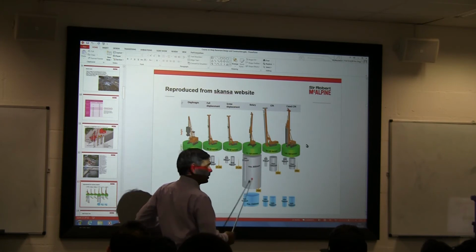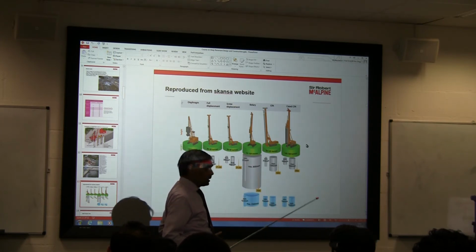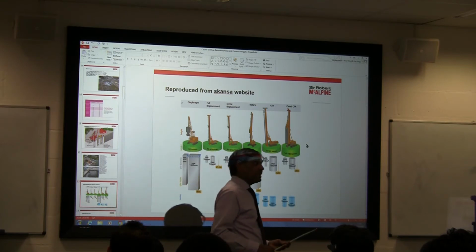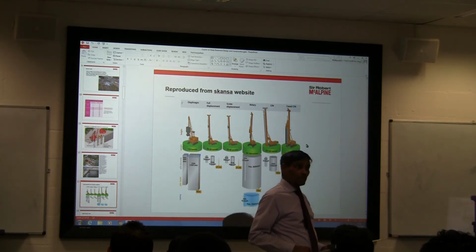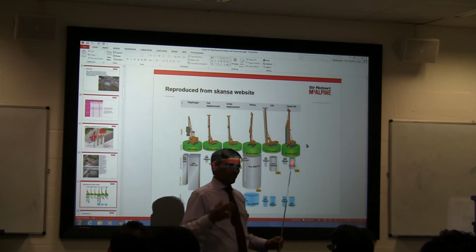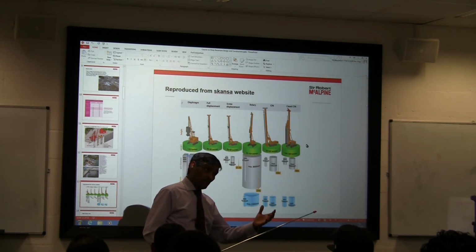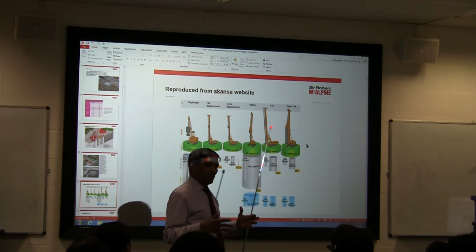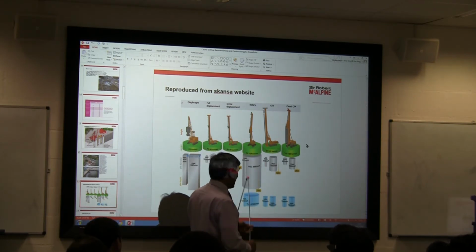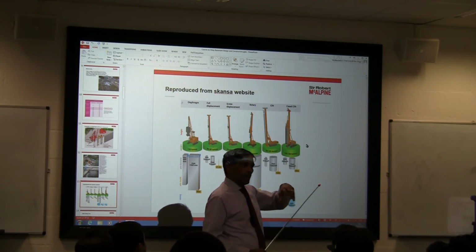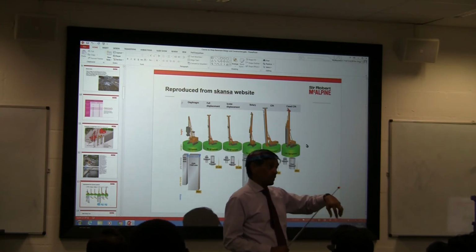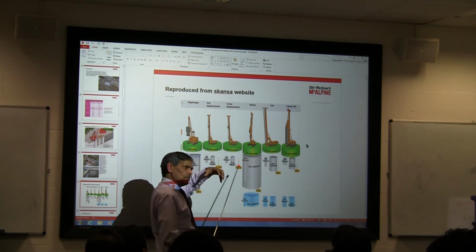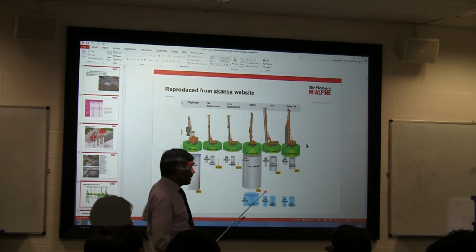And rotary drilling, if you are actually drilling by rotary means, you can go as much as you want, 75 meters. We are doing 80 meter piles in London by boring. So you keep boring. And then sometimes you have to use a temporary casing. When you go into hard stratum like London clay, it will stand up on its own. And now we are able to send a camera and look at the hole, look at the collapse of material into the ground as well. So that way we can control it. But mostly you'll find temporary casing is only used in the top layers to hold the ground.